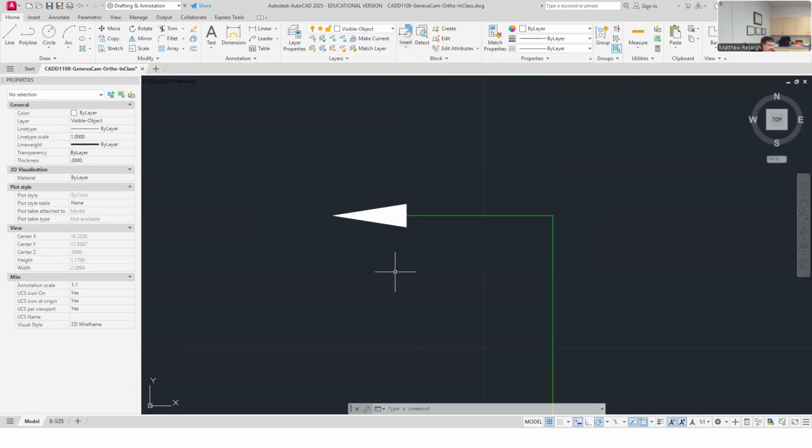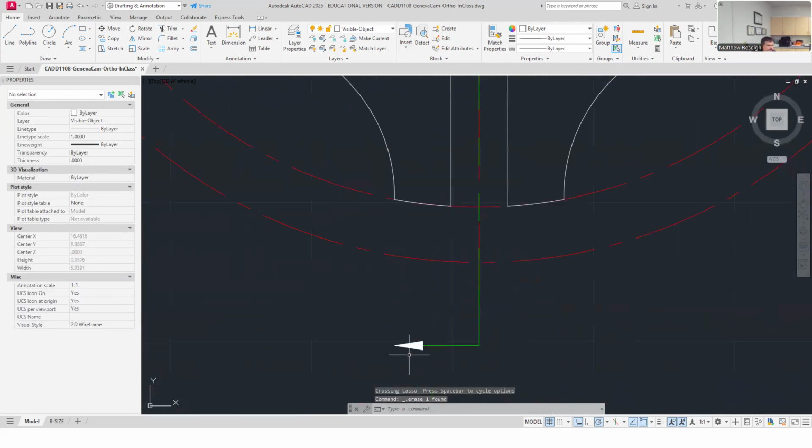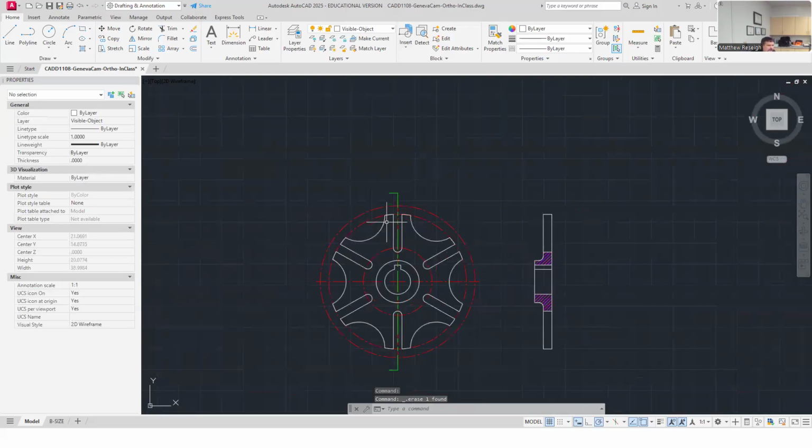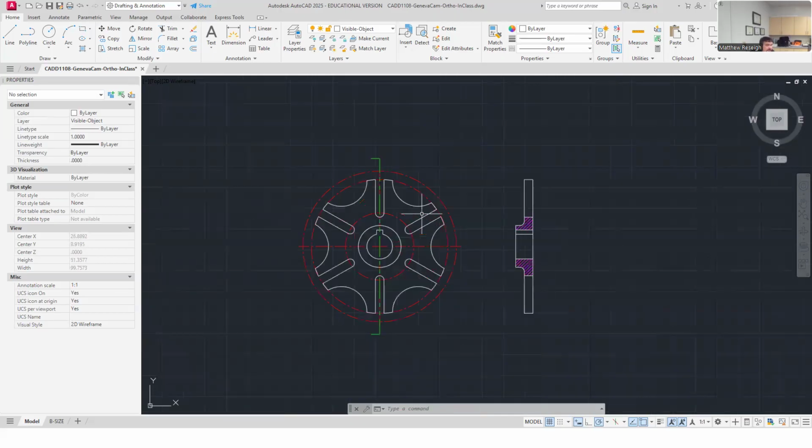So now I'm going to delete these things though, because these are kind of like non-annotative. Maybe I turn that one in, but I'm just going to make sure I delete the old ones that I had that I created my block from. Oh yeah, you could do that too, right? You could convert to block. Yeah, like if you select that object and it'll be like convert to block. And then just make that block annotative, whatever it takes to get yourself an annotative one. So essentially now I have a block for that.